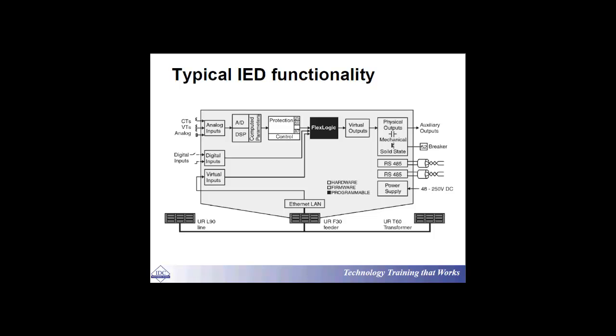I've got other protection control devices in there. They have got elements 50, for example, which is the instantaneous overcurrent. They have got elements 87, which is the differential protection. But whatever it is, they have got a logic. I can use devices like FlexLogic just to bring everything under control. As you can see, I've got analog and digital inputs and outputs, virtual outputs. I've got physical outputs. Not a problem. As long as I can control all these things, I understand which one is virtual, which one is physical, which one is analog, which one is digital.